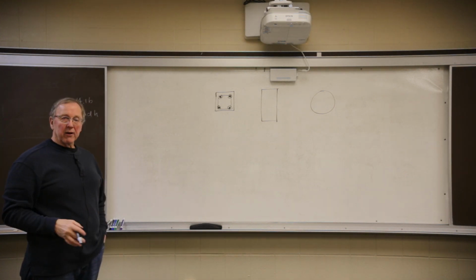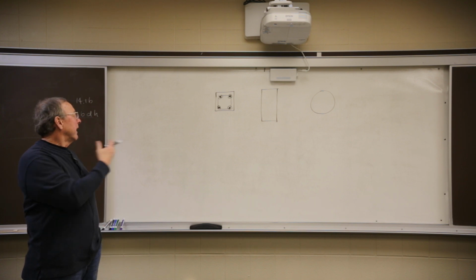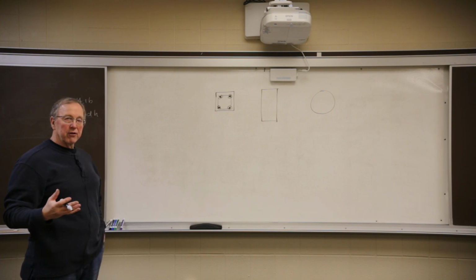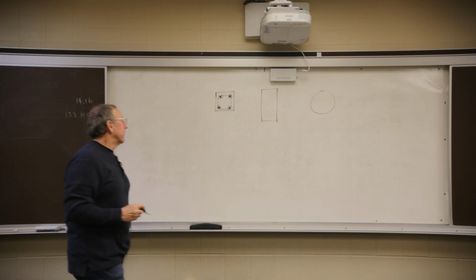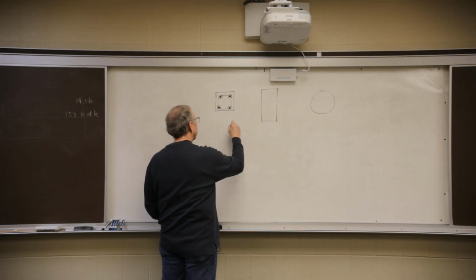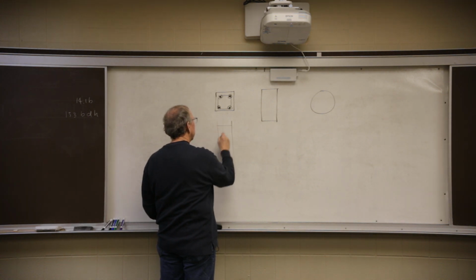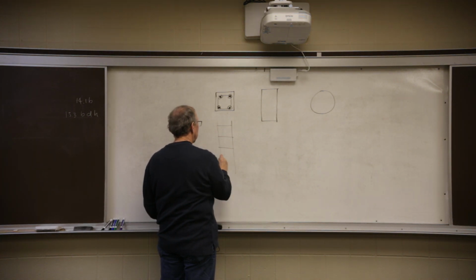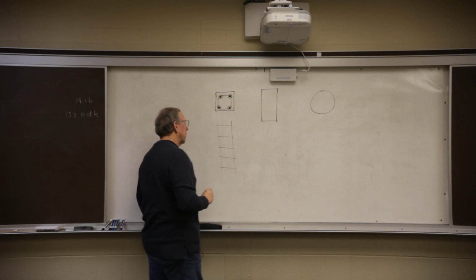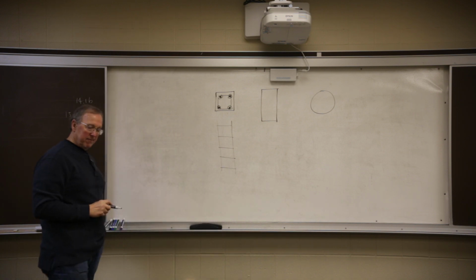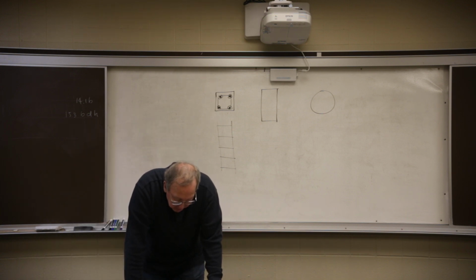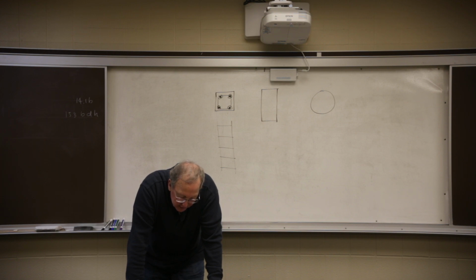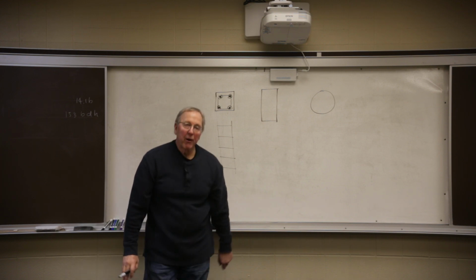Secure it, pour the concrete, and then we've got our cage in there with bars, and the cover will be maintained by spacing. So this, if you looked at it from the side, would look like this. There's my cage, and there's the horizontal ties. Okay, and it shows you there, it says primary forms of column reinforcement, rectangular layout of vertical bars with lateral ties. Then they got a circular one right next to it.